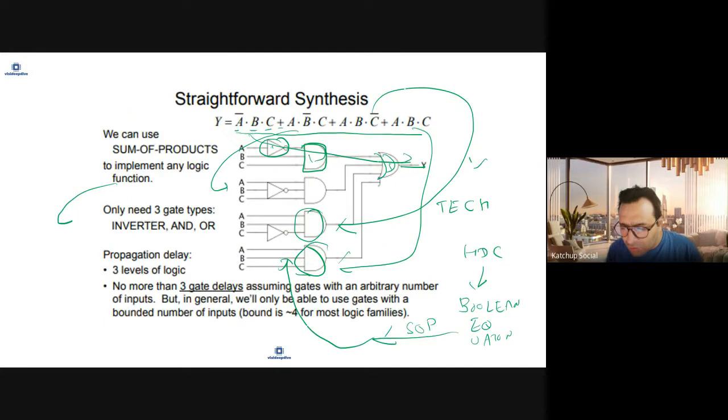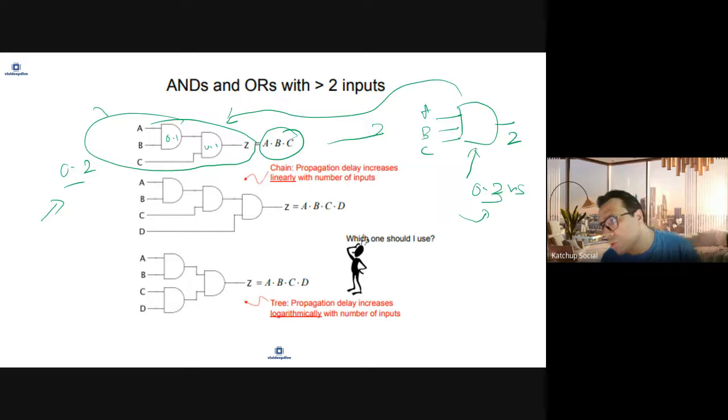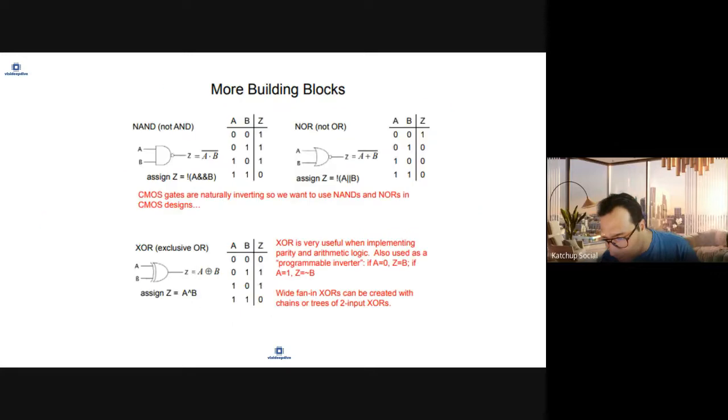So first it converts that into a Boolean equation. That Boolean equation is written in sum of product form. Then it chooses what kind of cells it wants to use. Multiple cell options exist, so it has to figure out which cell to pick, particularly depending upon what path it is or the area requirement. You can have more building blocks.